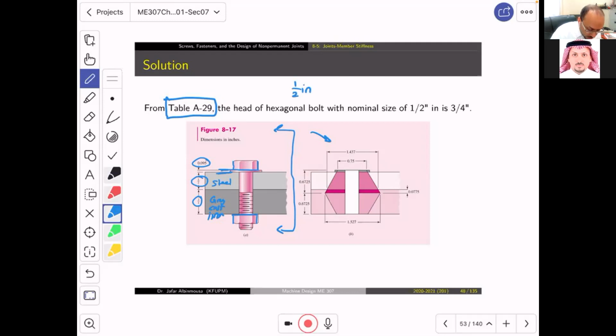And then we have 20 UNF, and then a cross multiplication sign, 1 and then 1/2 inch, and then SAE grade 5. I intentionally split these into 4 parts. This one, this one, this one, and this one.